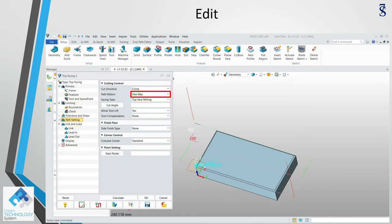And also there's an option. Because this is the final cut, we want to do it in one direction rather than zigzag, because ultimately the surface has to be flat. If we do zigzag, there is a tendency that the tool wear may cause the part to be uneven. So we will do one direction, to make sure that everything is even.